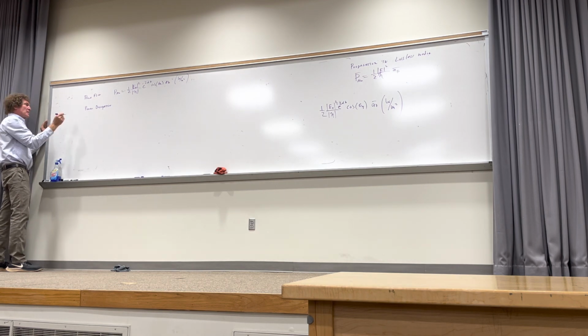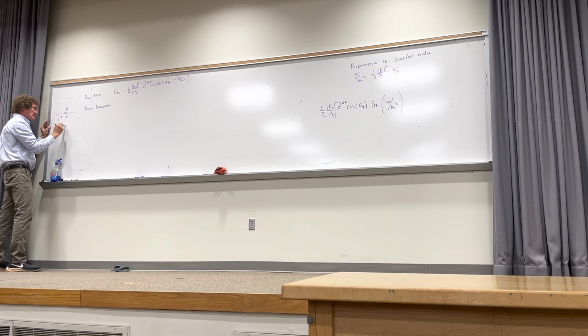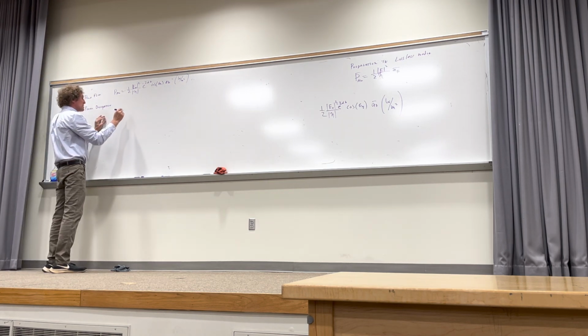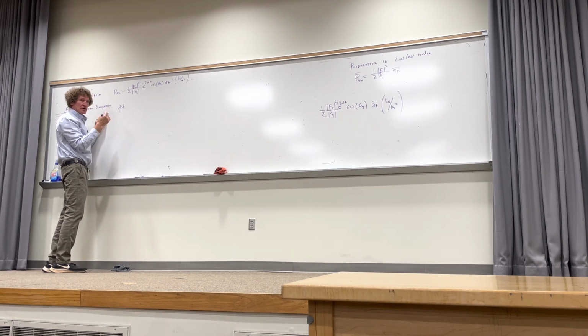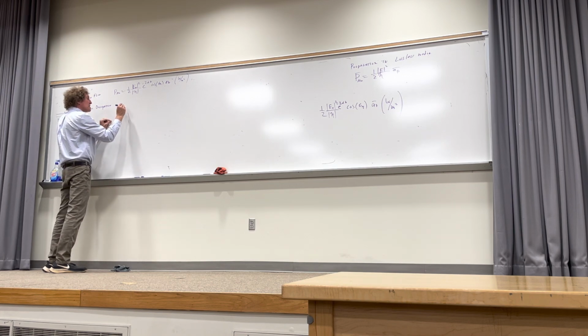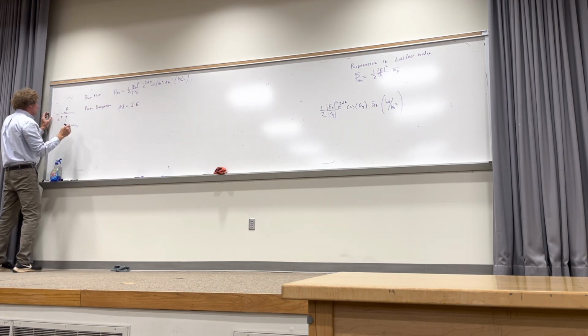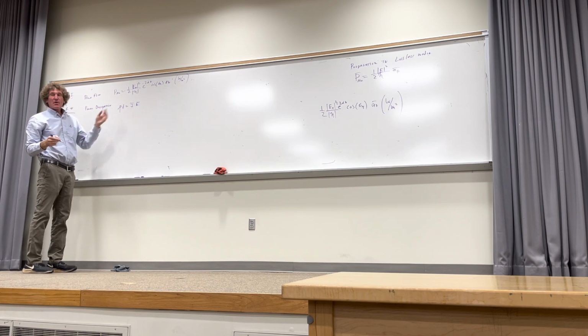all right, think about what is the power dissipation in a resistor if you have a current I. Say it's DC, what is it? I squared R, that would be in watts, right? All right, when we talk about power dissipation, you can call it P dissipated, that would be watts per meter cubed. This is dissipated now, it's not flowing, it's being dissipated in the environment, turned to heat. That's equal to J dot E. And by the way, I should have said, if there was a voltage here, V, then the power here would be V times I, right? And technically, this is for DC, I should conjugate it if it's AC, but y'all follow me how that would be the case?